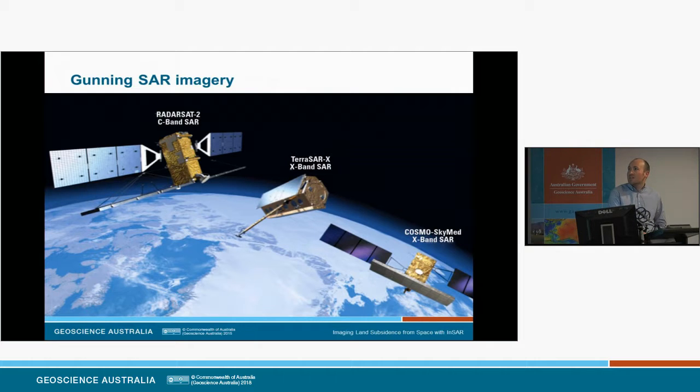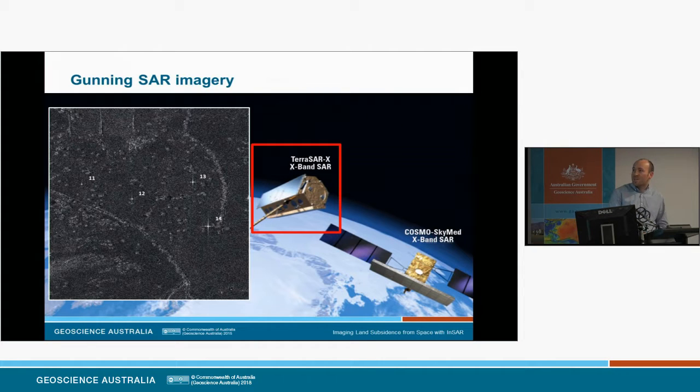If we look at the response of the corner reflectors in the TerraSAR-X imagery, this is what we see in the amplitude image. So we have 4 corner reflectors in the image here, as shown by where the laser pointer is pointing. And we have a size progression of these different sites. So this is the smallest corner reflector, 1 metre in size, 1.5 metre, 2 metres and 2.5 metres. So what you can see is a general increase in the magnitude of the response of these corner reflectors in the image. What you may also see is that the response itself is cross-shaped.